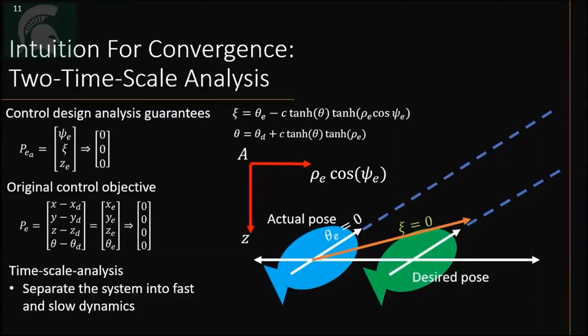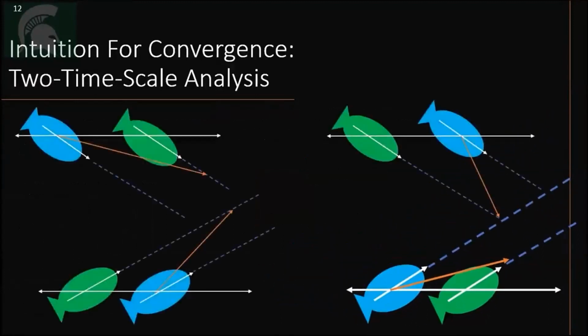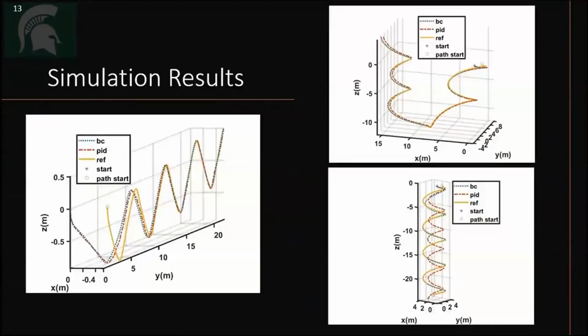So in essence, what the hybrid function is doing is sacrificing some pitch tracking accuracy in order to minimize the position error. And likewise, it can be seen to do so in other situations. The controller will simulate with an observer to determine the body fixed linear velocities, because in general, this is something that we can't measure with the robotic fish.